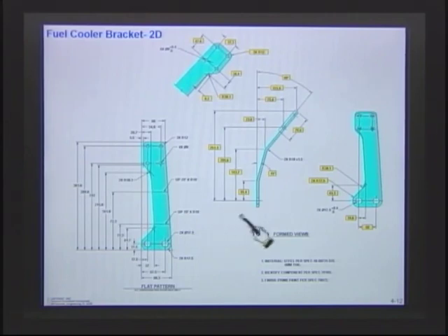Now this here is the actual detailed drawing, and I drew this thing up. The thing is kind of small. You should have a picture of this in your workbook. And notice this one has all dimensions on it. Now sometimes people will send this thing along and show you what all the dimensions are. And what I could do is apply the tolerancing to this one. That face there on the side would be datum A, the holes would be called off as datum B. That surface I put a profile on, and then that upper surface I put a position on.